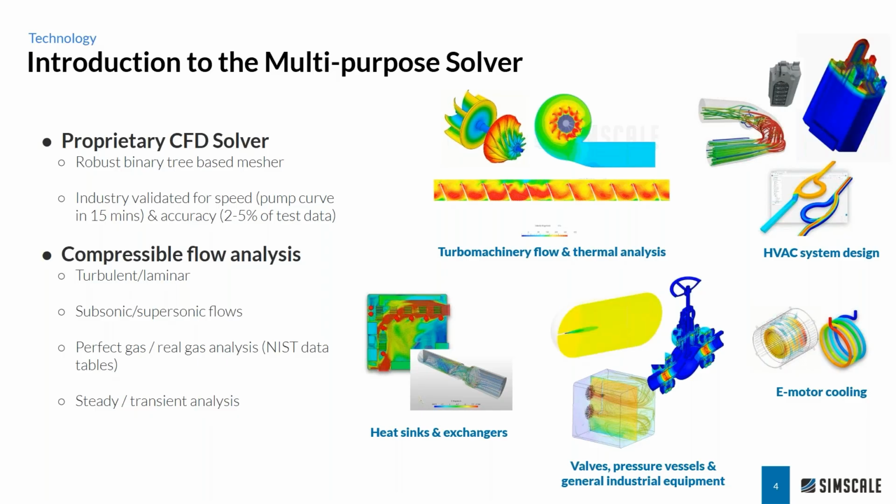As far as compressible flow goes, this solver is capable of handling laminar and turbulent, transonic to supersonic flows up to around Mach 5. In terms of gas behavior, perfect gas as well as real gas analysis is possible, and we will see that today in the demonstration, including steady and transient analysis.